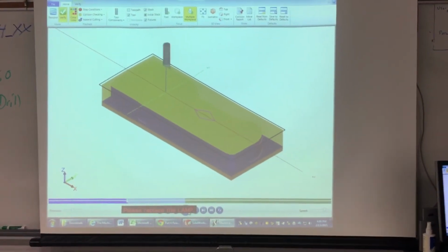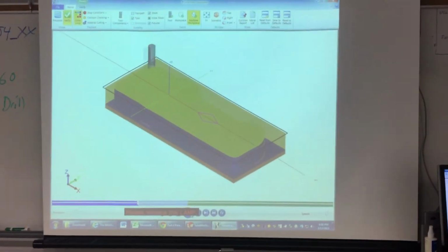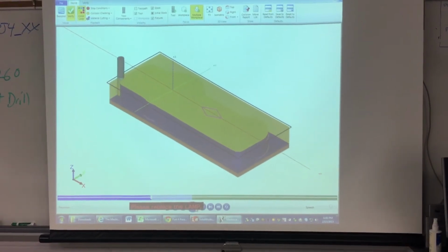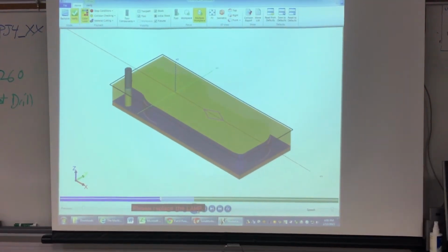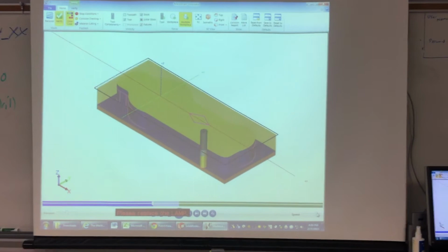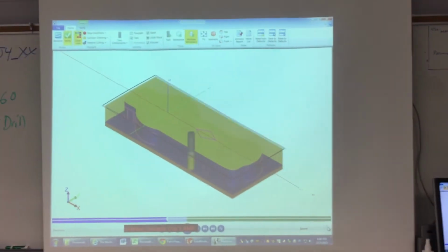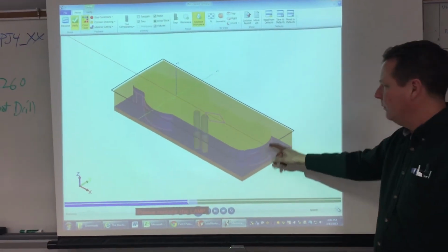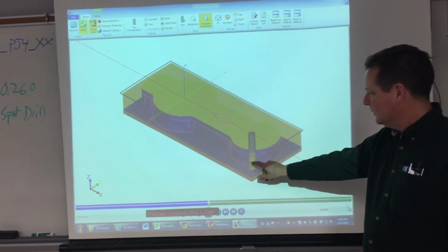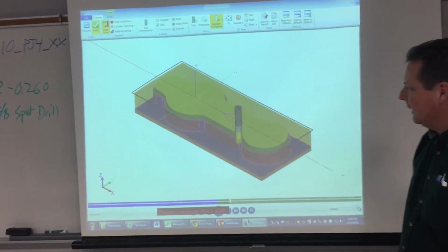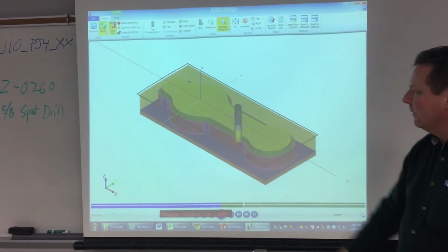If I had a 3/4 inch end mill, you know, I could up these times even faster. This Mastercam X7 in the new Verify shows that you left the geometry like that. Now here's the upper core.